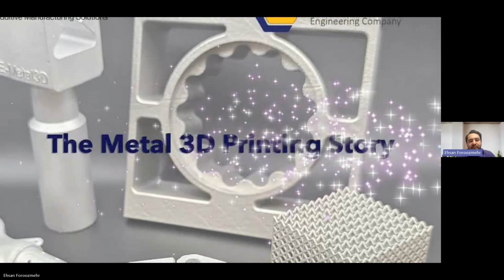Once everything is done, the part has to cool down because it's obviously very hot. And then we can open the chamber and remove the parts. What you see here, wherever hasn't been melted still remains as powder. The powder is taken away, sieved and reused. That is one of the main benefits of this technology that we'll talk about later.